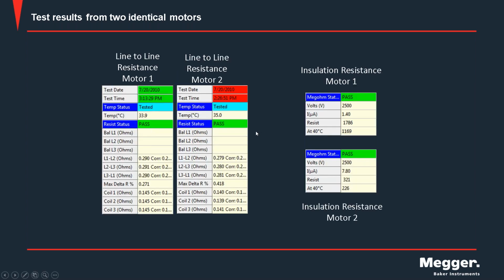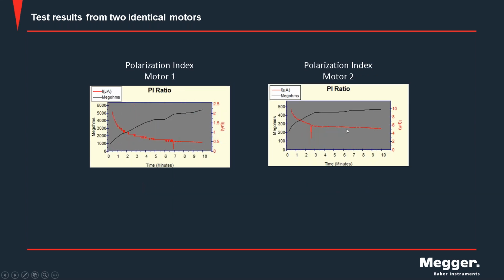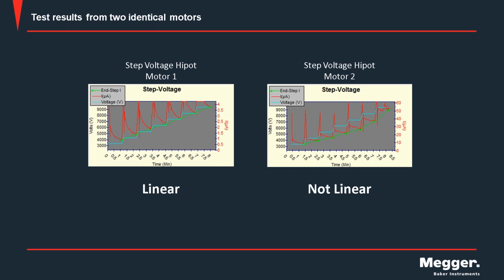Again, it's still passing, I believe. Actually, let's see what that PI value was, I believe it was like 1.9, so just below the threshold of 2.0, which isn't unusual for a field measurement, but again, giving us a clear indication that there may be something amiss here that we need to drill into and identify. Then we move on. So if we just left it here, we would have some questions, but it's 200 megohm, that's still good. We probably don't need to be worried too much.